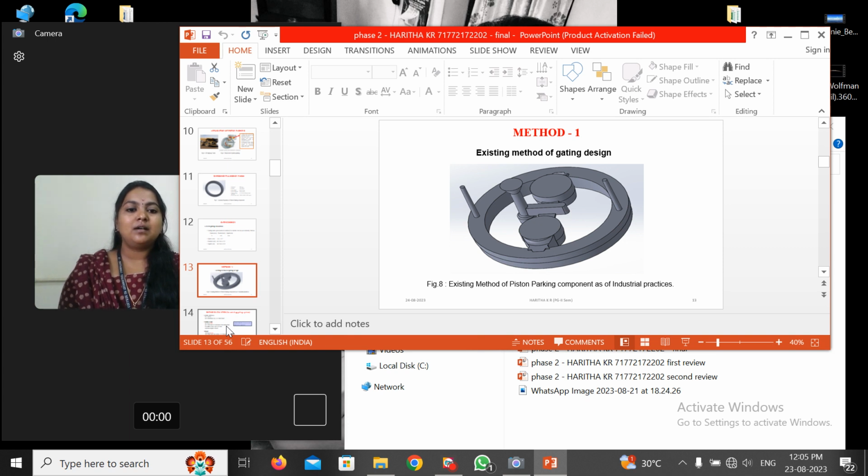The same design has already been set up in the pattern match plate. With respect to the size, I am measuring each of the runner, sprue, and in-gates, as well as the feeder base, and the vent component size has been measured. This design was made using the SolidWorks 3D model software, with respect to the process parameters